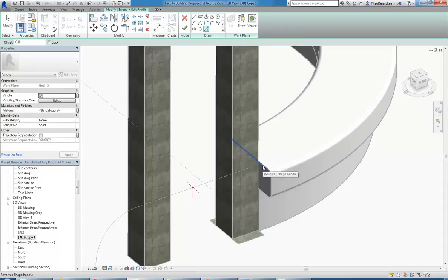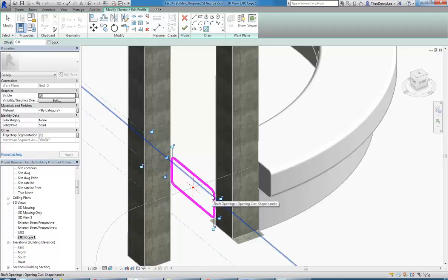And do you remember what to do to get a chain of lines? Yeah, exactly. You can just tab there and get that whole edge with one click. So clicking there, now you can see that the shape has gone over to the left there, but that's exactly what I want because it's gone onto the profile plane. So it's projecting from the revolve onto the plane I'm working on.